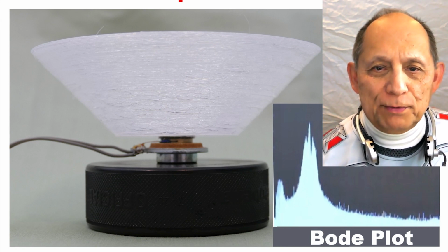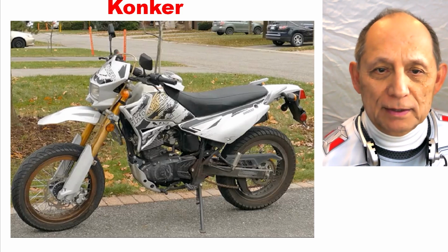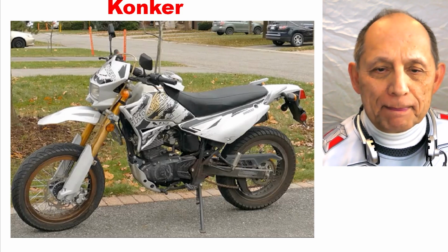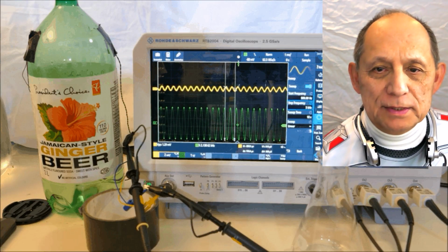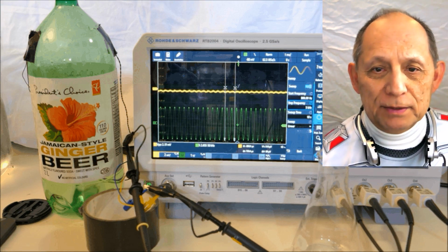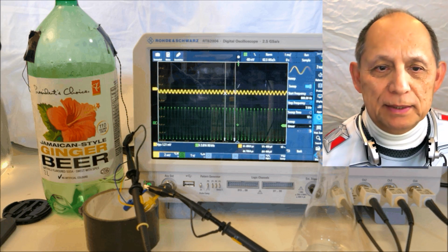I also used a waveform generator to figure out how much fuel was in a fuel tank by searching for the resonant frequencies of the air cavity in the tank. Again, sweeping frequencies, I used an audio driver to vibrate the tank and a piezo disc to detect the acoustic resonances where the signal peaked.